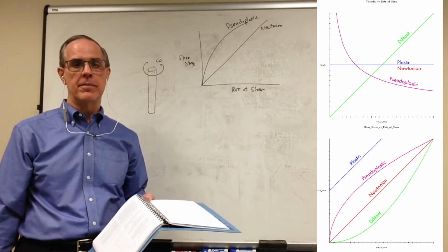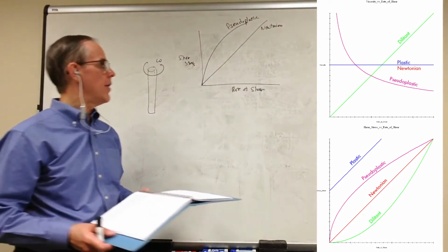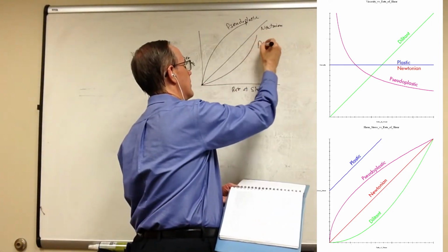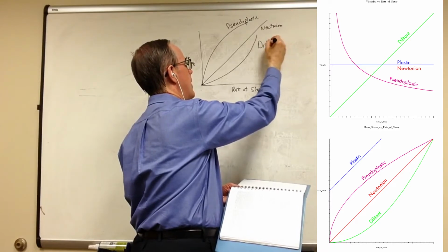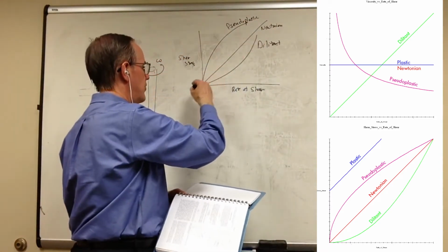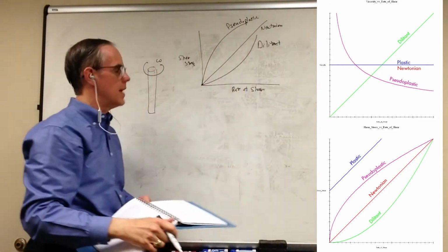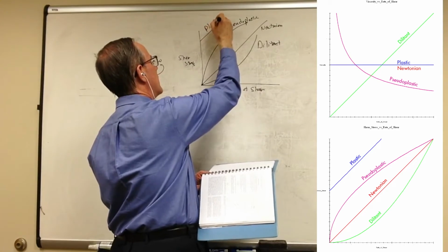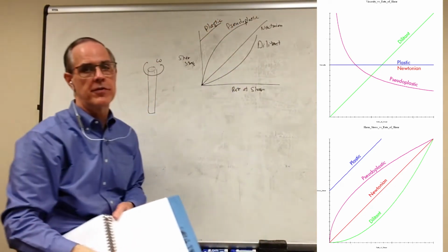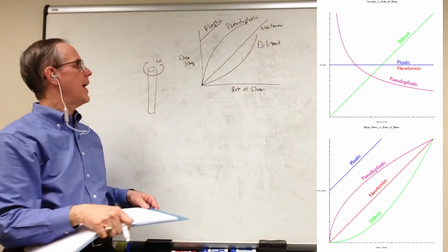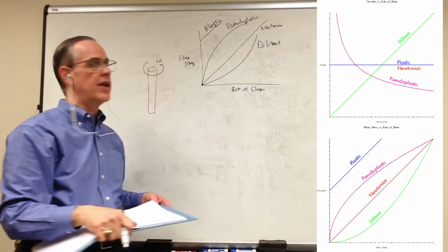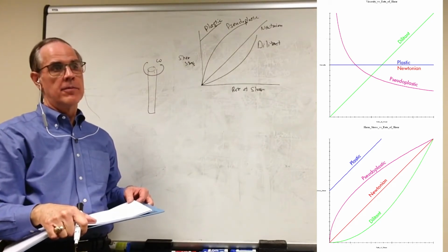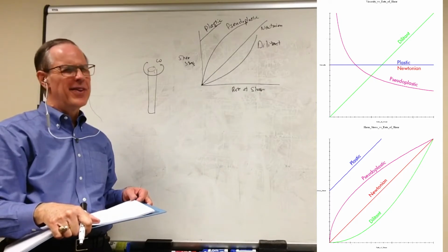you used to see in the movies sometimes. On the other hand, if you have a fluid that starts out dilatant, a dilatant fluid starts out with a slow increase and then comes very rapid. And then you've got purely plastic fluids that really are in the twilight zone between fluids and solids, where they actually have a shear stress at no shear, which violates the definition of fluid that I gave you earlier, but they are fluids and not really solids.